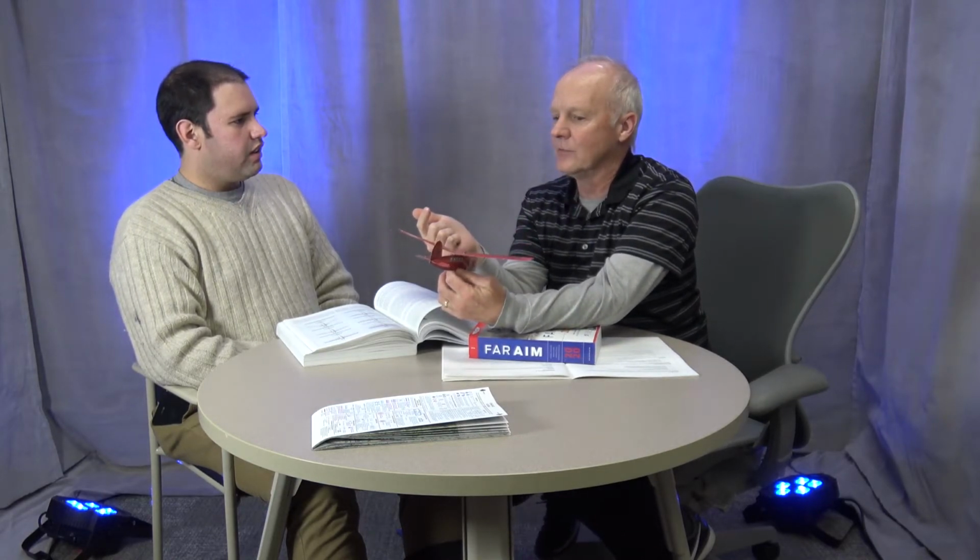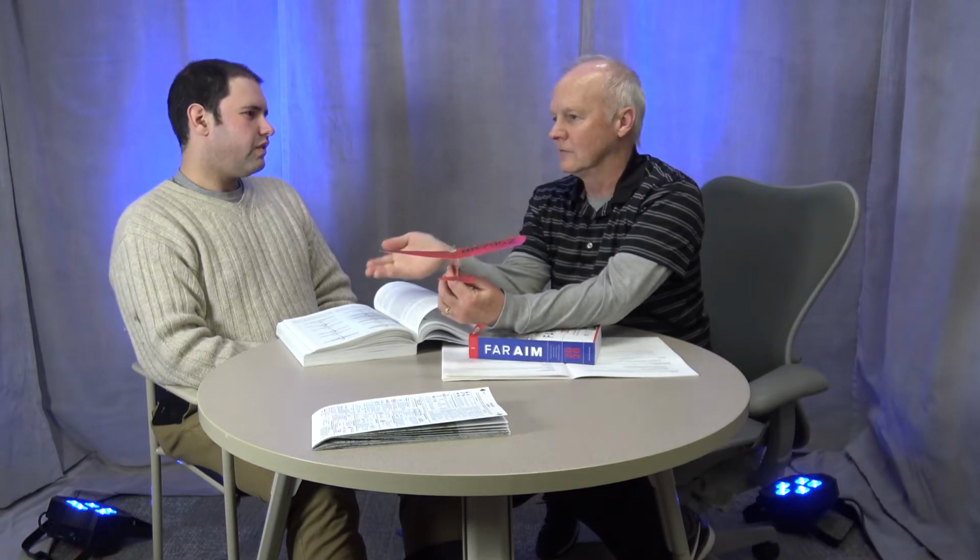Because I had an RC plane once. It was just a flying delta wing. And I could not... It just wanted to pull right, and torque should have pulled it to the left. It just wanted to roll right, and I was fighting it. Come to find out, I held it by the motor in the nose, and it just fell because it was too heavy on one side. I just glued a weight on the other side and solved the problem. But they didn't talk about that much in the book. Yeah, I was wondering if that was something that's ever a factor with planes.